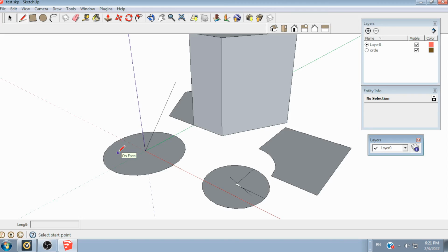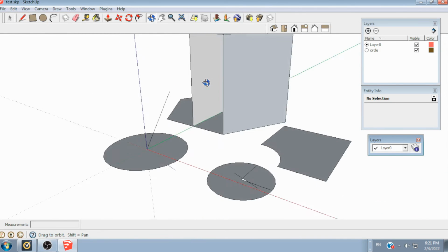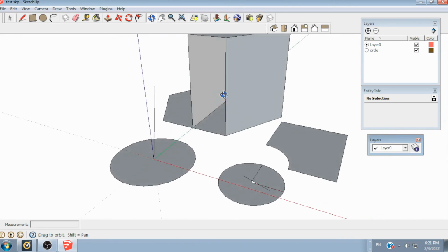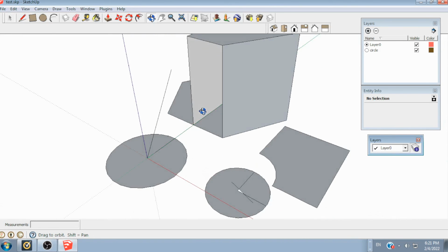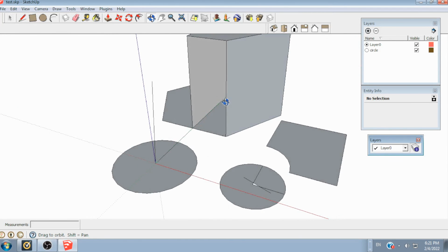I will make one other note that there are no coordinates per se in Sketchup, and there's no inside solids. Everything here is just a surface. If I delete that surface and look inside there, it's just hollow. There are two sides to things. You can see sometimes you have different colors on here. You can enable shading or not, which sometimes is helpful. The sidedness becomes useful when you get to do things like creating STL files for 3D printers. And then that becomes more important.